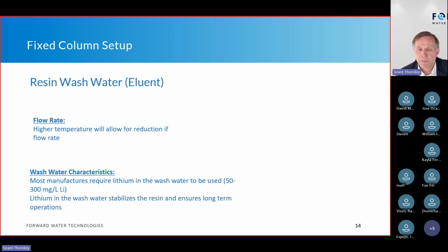Extraordinary lithium recovery, because what's happening is you're literally sucking the lithium out of the crystal structure, the matrix, and you're destabilizing it; you're going to collapse the resin. So if you're running 5 cycles, that's great, you're not going to see anything. But if you ran 30 cycles, you would see the lithium basically destabilize and collapse on itself.